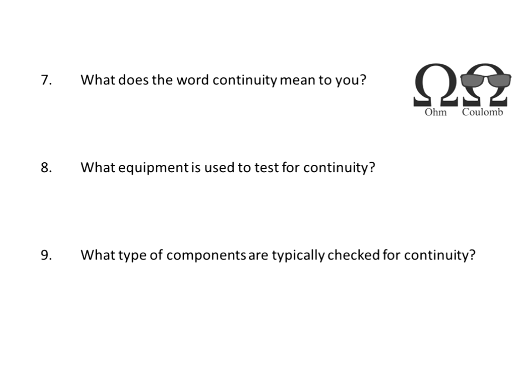So inductors, or just checking the connection of two wires when you're building a panel perhaps, or checking the primary and secondary of transformers, those would be used. You could use a continuity checker to check that.